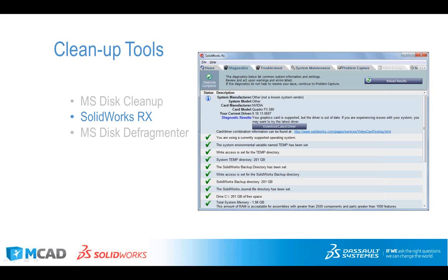Just a reminder that the main cause of crashes in SolidWorks is related to graphics card driver combinations, and the newest graphics driver for your card isn't necessarily the best for SolidWorks. The SolidWorks and card developers work on having a driver that is tested for SolidWorks usage.